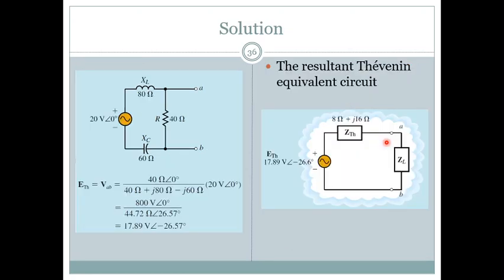When it comes to voltage, you just measure the voltage here. You have 3 impedances in series, so the voltage here will be the voltage division. So the 40 divided by 40 plus j80 minus j60, right? Again, you don't have to go to this step. So from here you get VAB is equal to